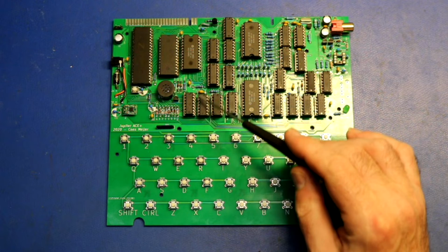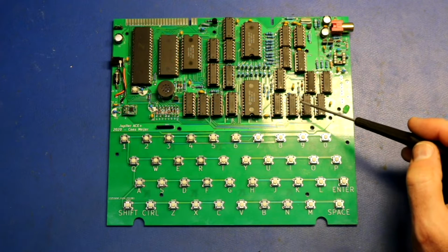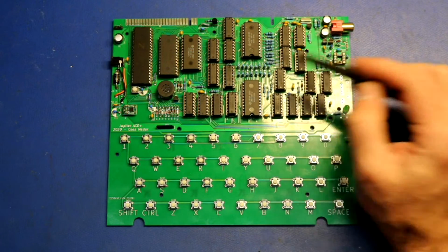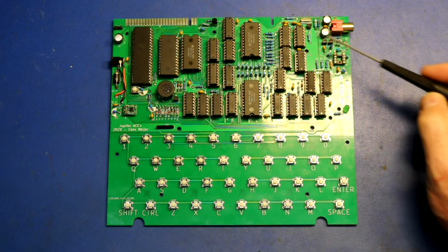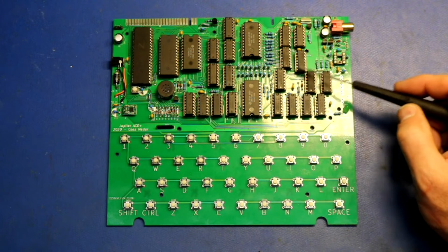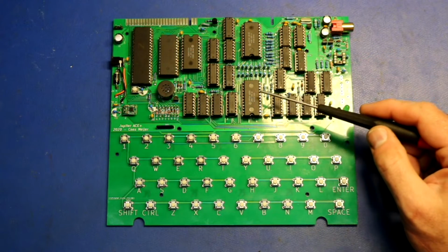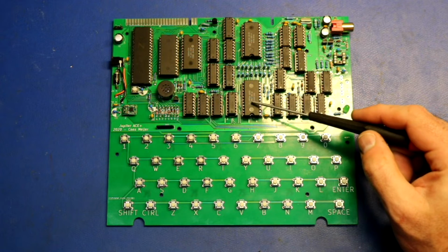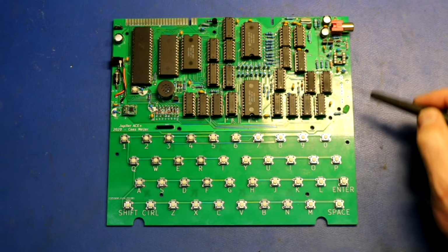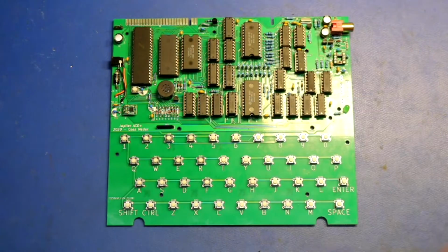And then the rest of this is all just logic ICs, so 74LS logic. Lots of 367s to do bus transceiver type duties. This thing doesn't have a graphics controller in it. It's all done using various counters and other logic over here that sequences through the video RAM and then takes the video RAM through the character set RAM and uses it to generate pixels. So that all happens over here in this section. Then you've got your expansion connector out the back.